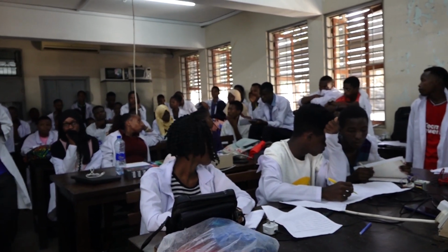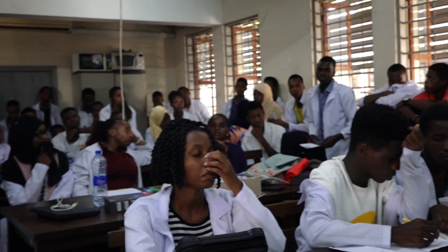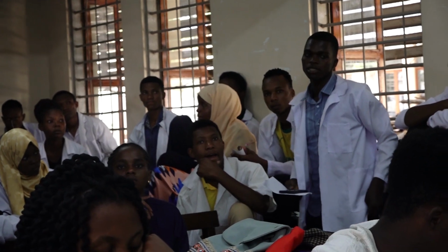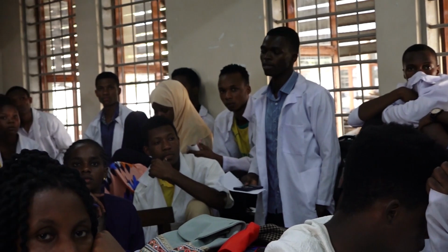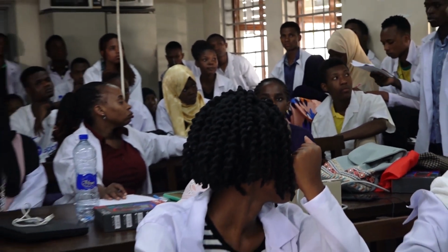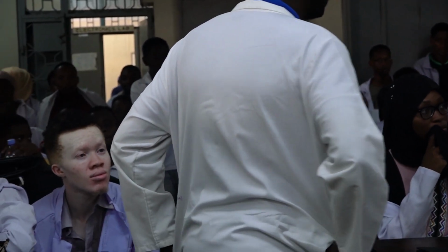Hey, who can try? Welcome. Speak loudly. I think the value that we get from the multimeter is the root mean square value. But the reading from the oscilloscope gives the maximum voltage, around 9 point something or 10. Then the manufacturer's value: he said 60 volt. What is the name of that 60 volt? It is the root mean square volt.